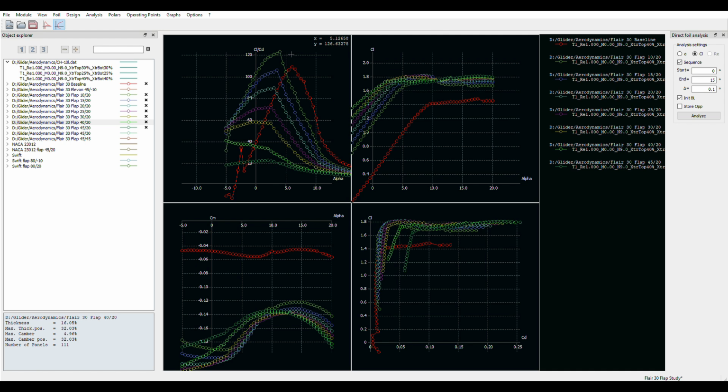And in the aero engineering world, this is somewhat known. Not everybody is aware of this fact. And that's because when you're trained to design aircraft, the professor will stand up there and say, well, you know, to size your ailerons or your flaps, just start out with a chord of 20%.